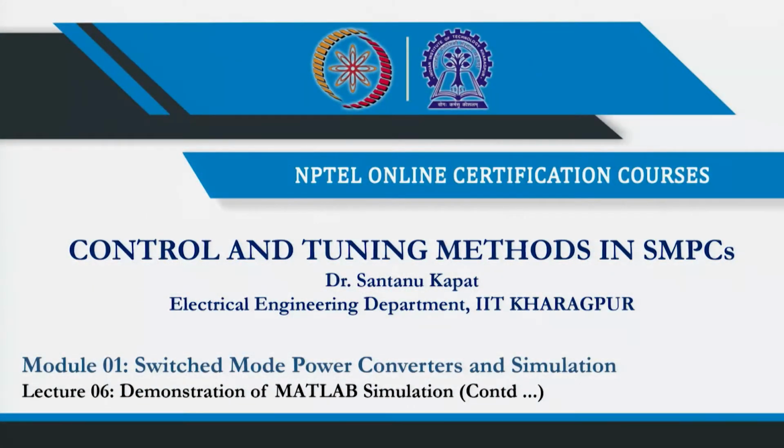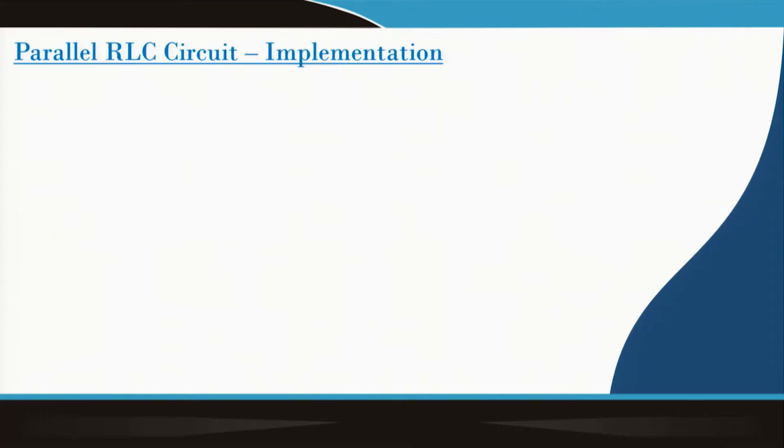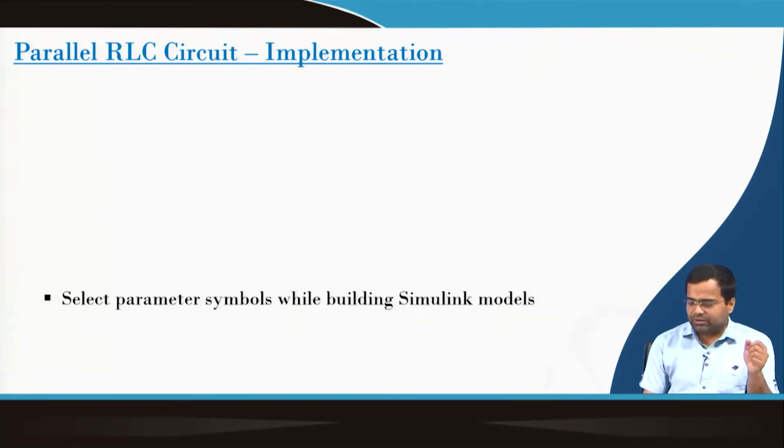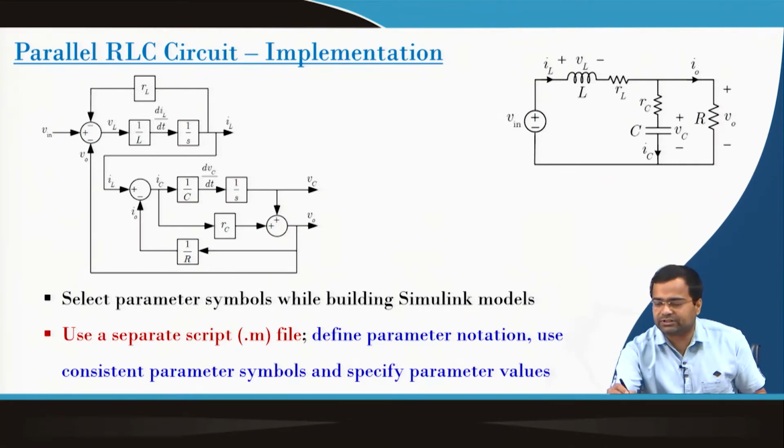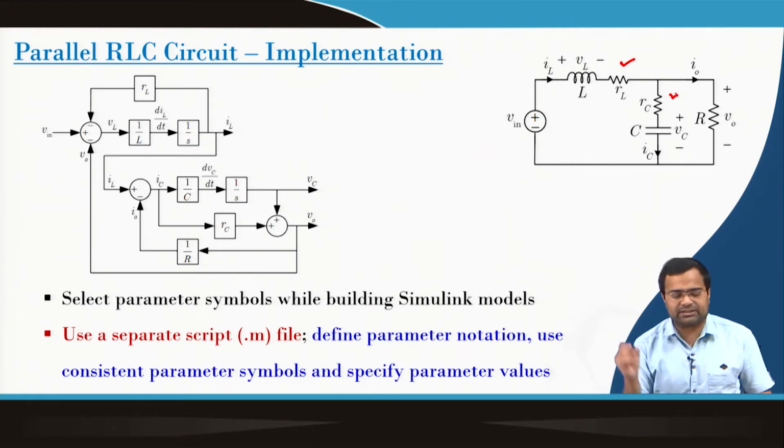Welcome back, and this is lecture number 6, which is the continuation of lecture 5 regarding MATLAB demonstration. So, in this lecture, since we have already implemented a series RLC circuit, now here we want to implement a parallel RLC circuit with parasitics. That means we are considering the inductor DCR as well as the ESR of the capacitor.